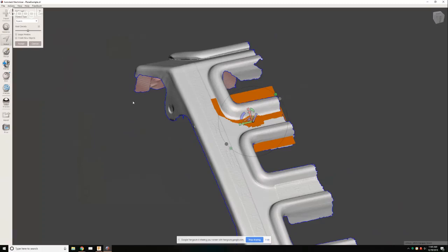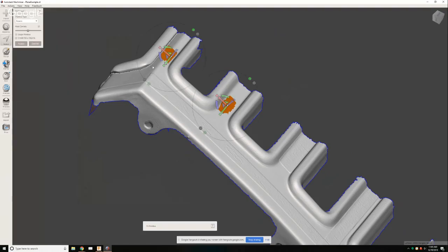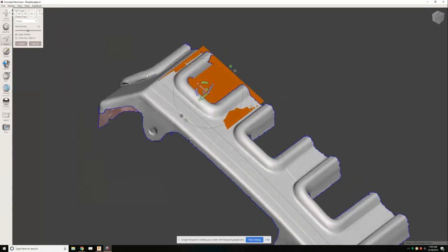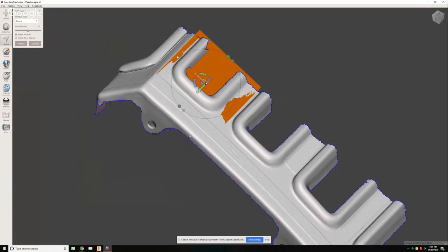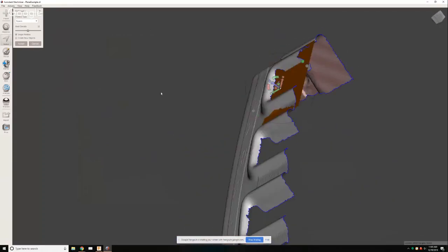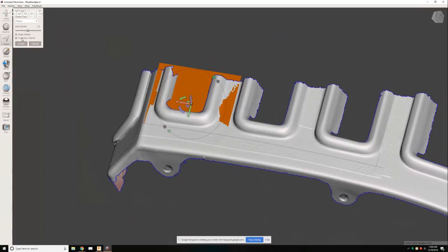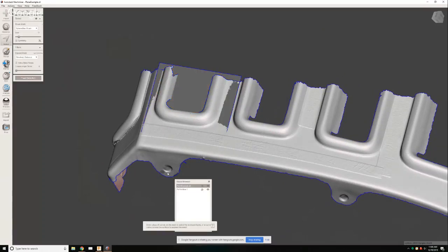But what I can actually do is select the flat place on this side and even go down very small here and select the flat plane on this side, and I go to the fit primitive command, and I select up here and say single primitive. What that will do is connect those two selected areas with a flat, absolutely flat plane. And I'm going to say create new object and click accept.